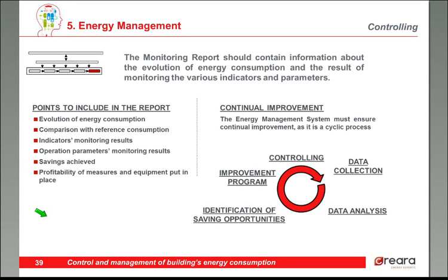Then creating a report is also very useful and very advisable. These reports should contain information on the evolution of energy consumption in the last period, comparison with reference consumption, and the result of monitoring the several indicators and parameters. Also, economic information should be included. This is also very important, like, for example, the savings achieved or the profitability of the measures undertaken.